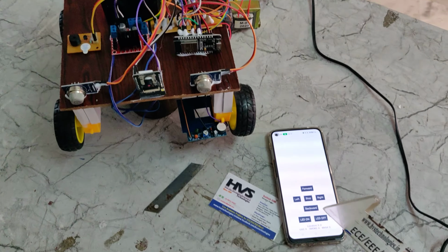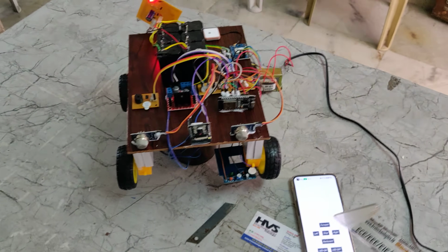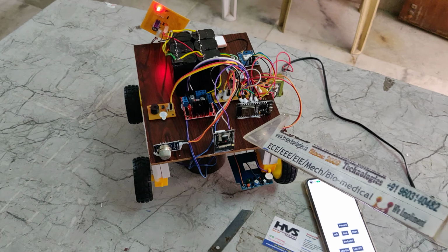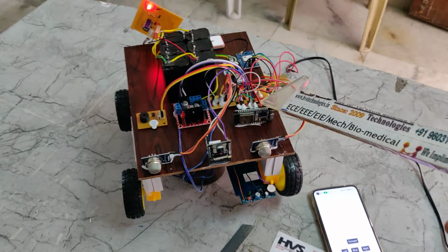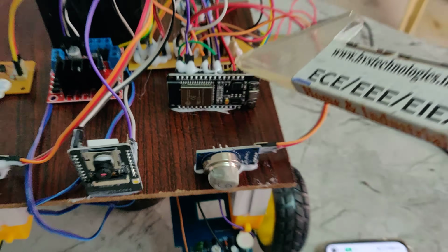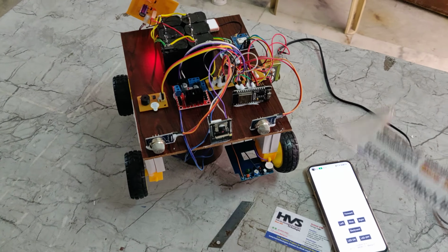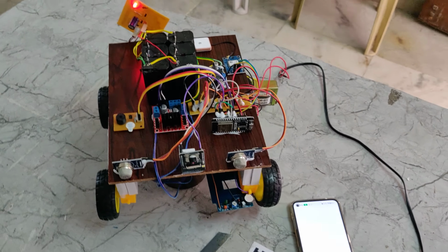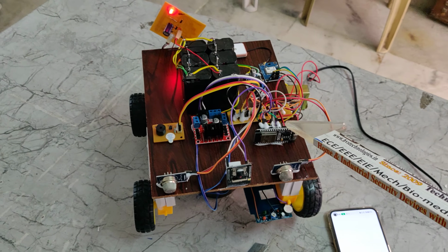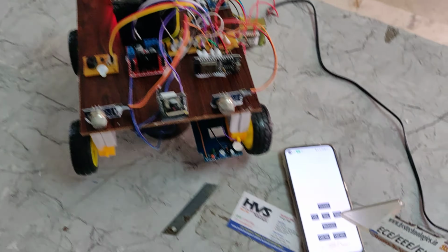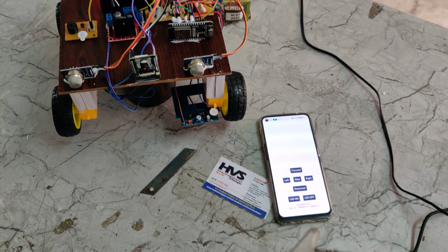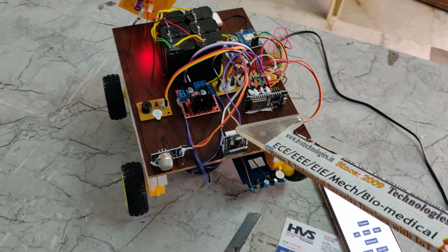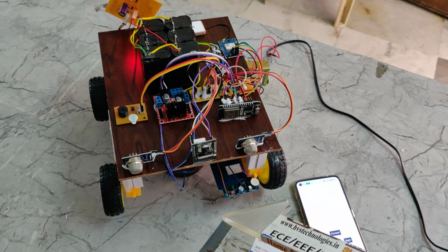So whenever we provide commands to control the robot movement, forward, backward, left, right, stop, these commands will be sent from the ESP32 camera to the ESP32 module. So we are using the ESP32 module here. At the same time, the gas, smoke, or metal sensor status will be sent from the ESP32 to the ESP32 camera, and that will be uploaded on this browser. So this is bidirectional full duplex communication between the ESP32 and the ESP32 camera. These are the main features of our project.